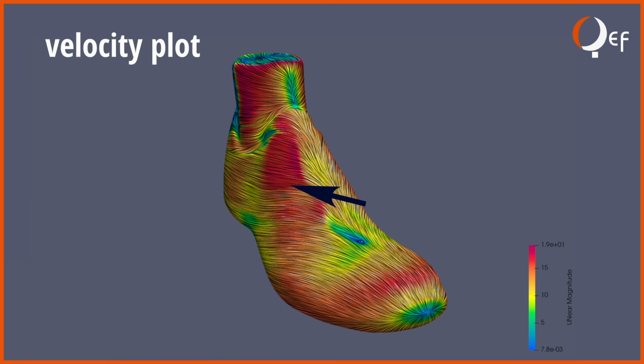The red areas where velocity is high are followed by yellowish areas where air is still moving and, as explained earlier, will remain attached to the surface. On the ankle, however, after the red zone, the velocity color turns quickly to blue, indicating a sudden slowdown in airflow separating from the ankle surface.